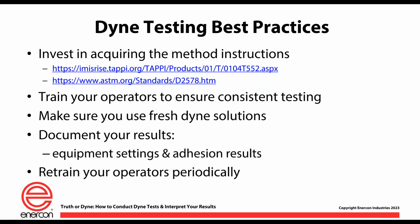The fewer people you have in charge of this testing, the more you increase your consistency, and your results will show better consistency. And then, like everything else in our process, whether we're printers, coaters, laminators, or film extruders, we've got to retrain people from time to time. People forget, and you get new people in. Retraining on a regular basis relative to Dyne testing is pretty important.